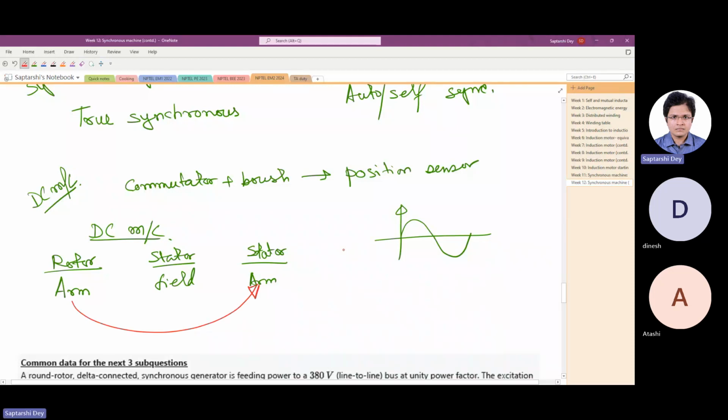Okay. And what will be there on the rotor? The rotor must have permanent magnets. Otherwise, again, you have to have a slip ring brush gear for the field, like a synchronous machine. Very well then. Now we have no brush, and the machine that we get by switching the rotor and the stator circuits is BLDC, brushless DC, no brush. But the problem is the commutator is gone.